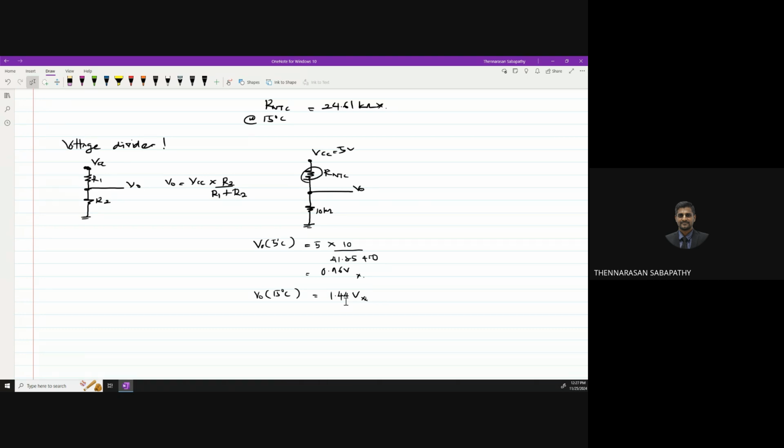The ADC on the Elvis, the Myrio, works with 5 volt, so approximately 0 to 5 could be used, but our device is now only giving a voltage from 0.96 to 1.44, which is very small, not even 1 volt. This won't give good sensitivity later when you design this as a whole sensor system.